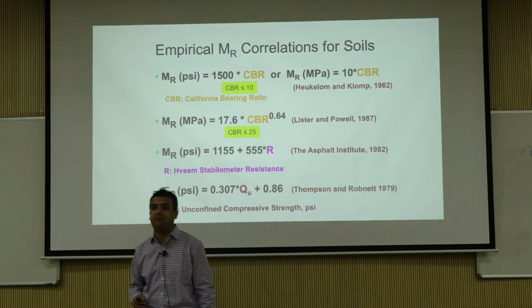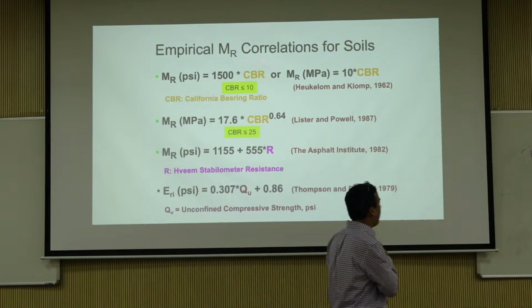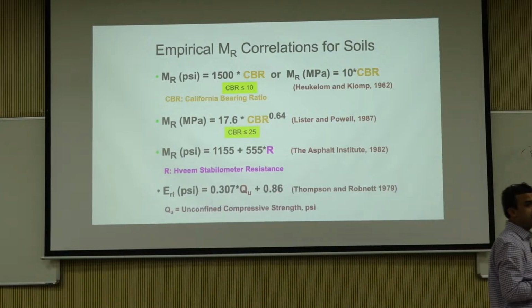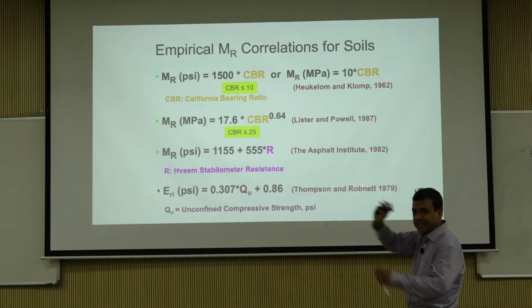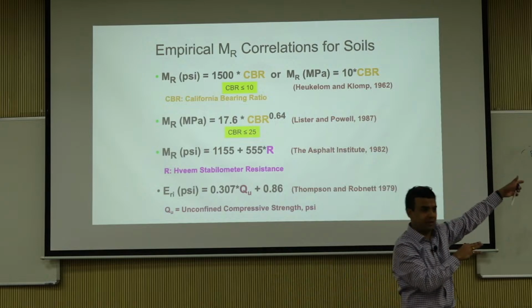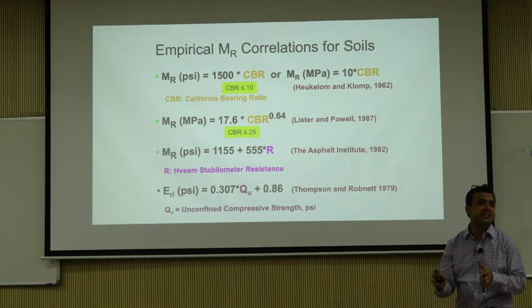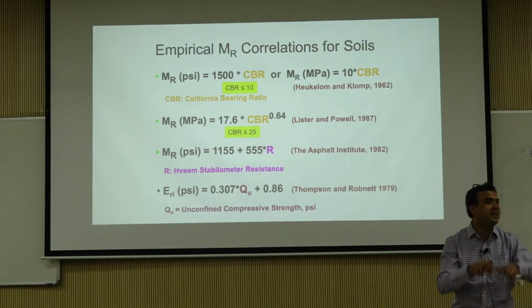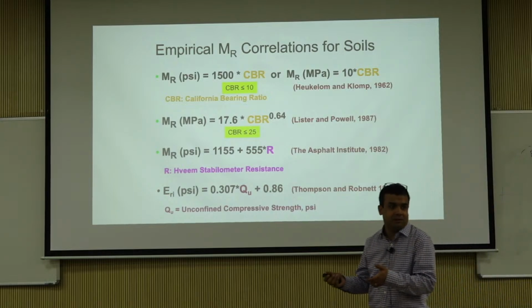This is again, folks, let's see your memory. What level of MEPDG is this going to be? Mechanistic empirical, I said there are 3 levels of designs, remember? This is 2, right? You test something and you are predicting something. That's what is happening, right? But again, I think by now you all know we should not be using CBR to predict MR because it's a different test, blah, blah, blah, all of that. But when you don't have anything, you have to. Just have to, right?